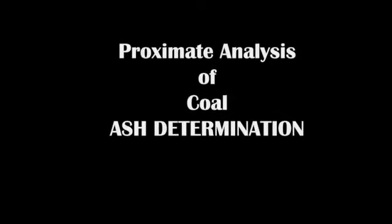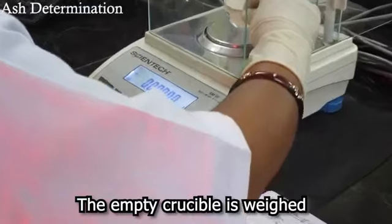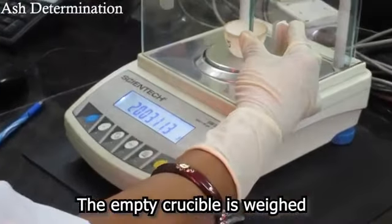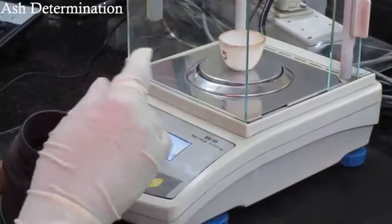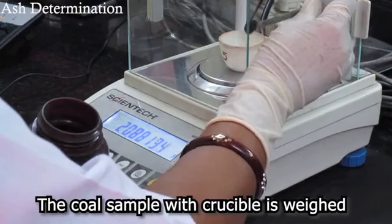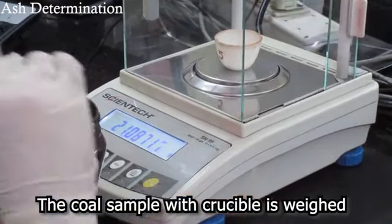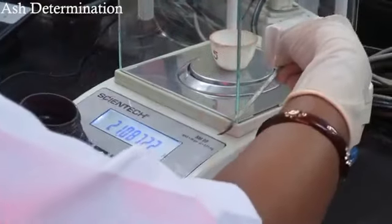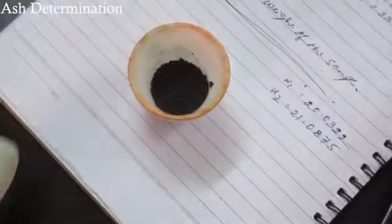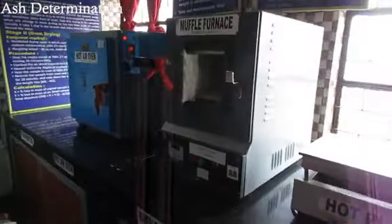Let's learn about ash determination. 1 gram of lab sample, minus 212 microns, is taken in a dry weighed clean empty vessel made of silica or platinum. The coal sample is evenly spread out to prevent formation of lumps.